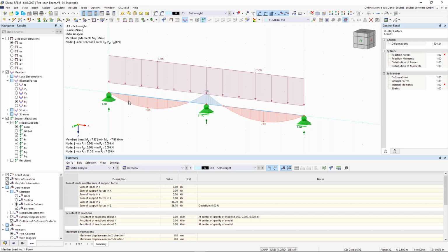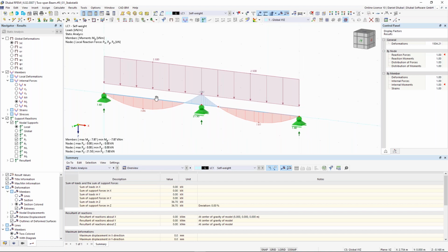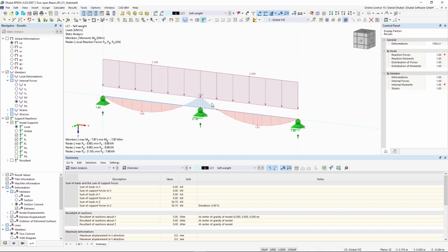So the previous beam had one degree of freedom free, so when you calculate it with the force method, you need to find this undefined value, and with this hinge we make it statically determined, and this is a huge advantage. So yeah, let's continue with the poll.